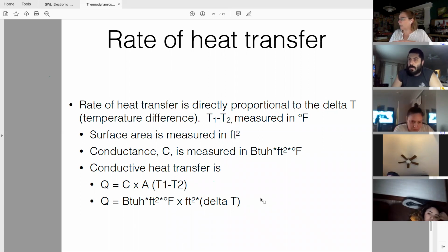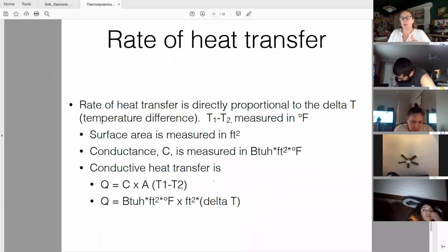Today, we looked at the psychrometric chart, which is about our dry bulb temperature, our wet bulb temperature, our air temperature, which is the dry bulb, the moisture content in the air, and how those all relate to each other, how air holds different amounts of moisture at different temperatures.